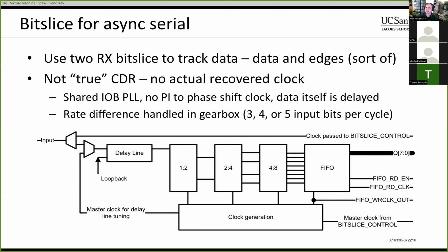And I think in large part because of how the clock network works. The PLLs that drive the IO components are located in the IOBs, and there's two PLLs for the entire IOB. And like I said, you can put like 12 channels potentially inside of the IOB. All of those 12 channels, you only have two PLLs.